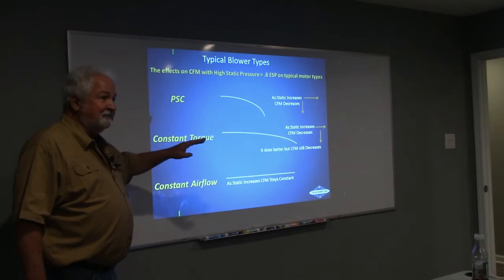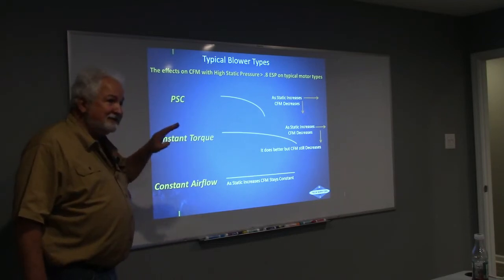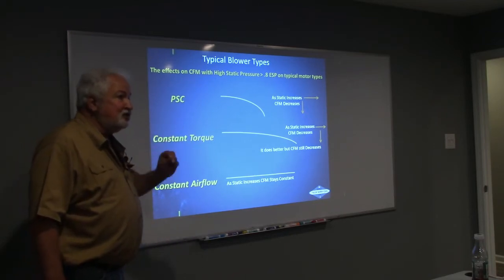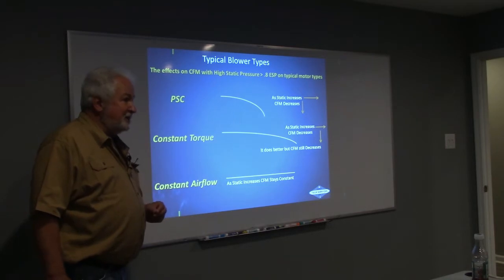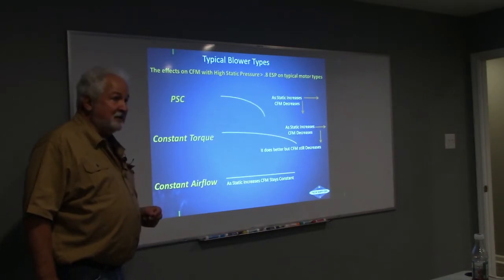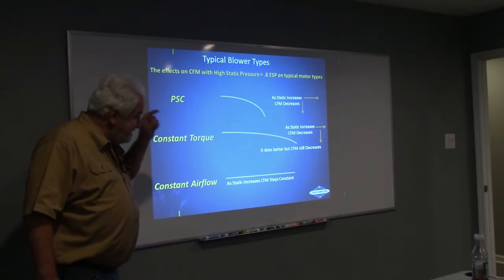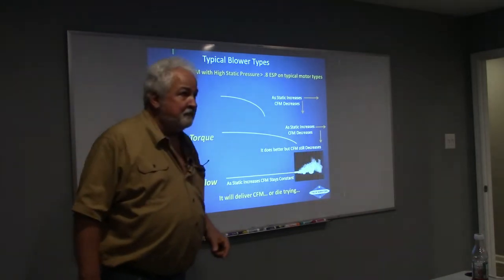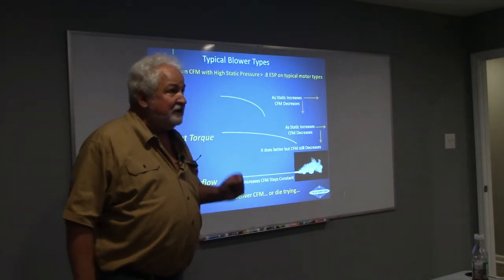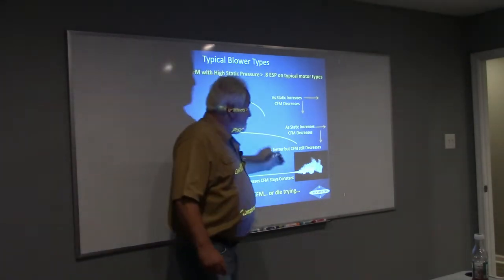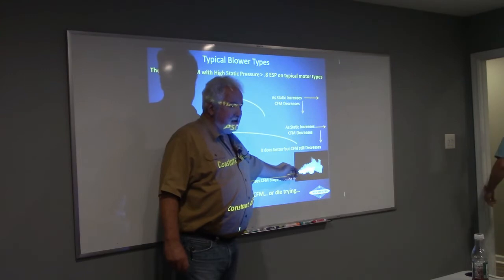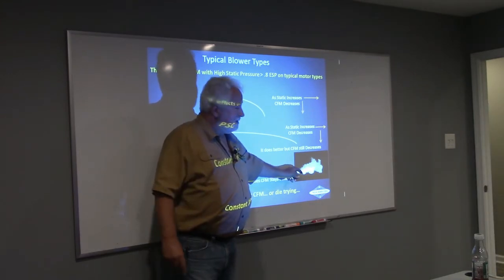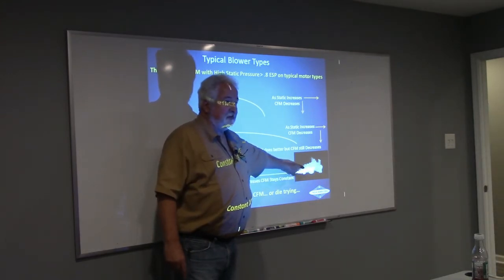It's gonna stay doing the same thing. It's gonna get you that CFM because that's what it's designed to do. You increase that static and it's gonna get you that airflow, or it's gonna die trying. As soon as you get that static pressure up in that 0.8, 0.9 range, right? I'm gonna smoke that motor.